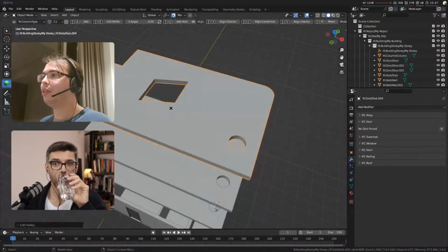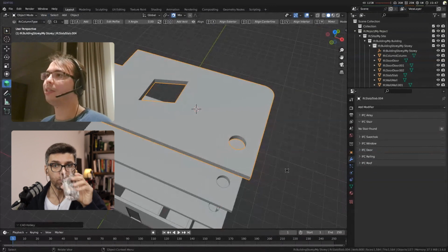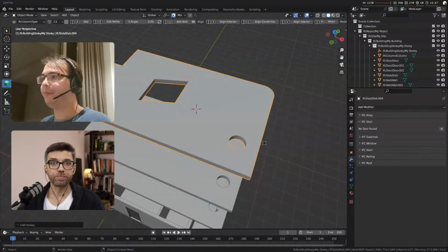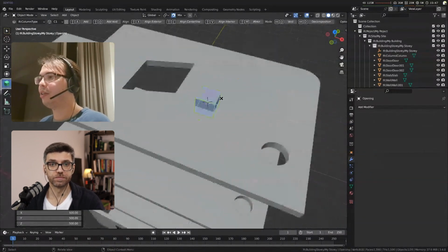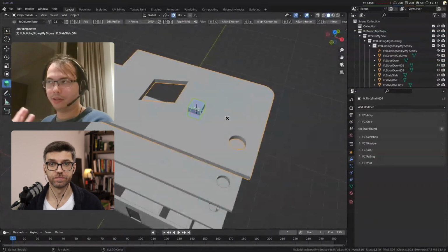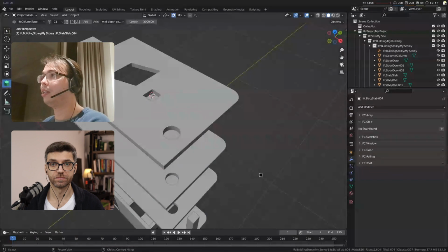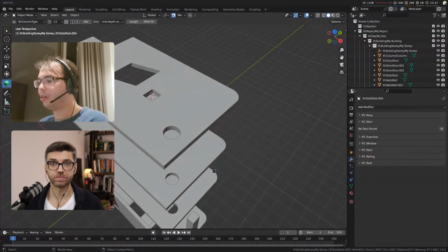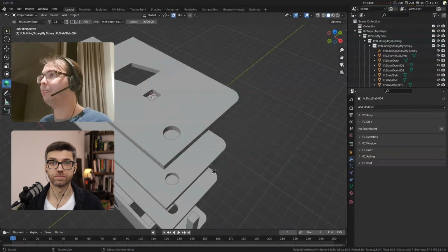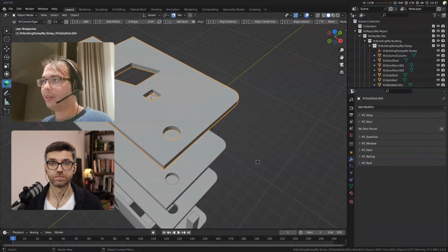So, for example, in this particular slab, if I wanted to, I can create an internal boundary of the profile, or I can create a semantic boolean. I can say that actually I want to go and add a void. So this will be my void object. Let's go add the void there, and there we go. I have my void. So yeah, you can do those.